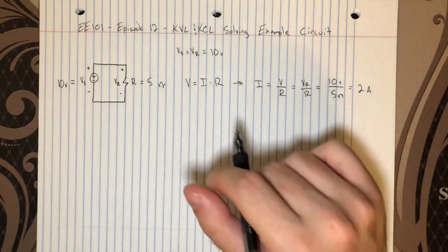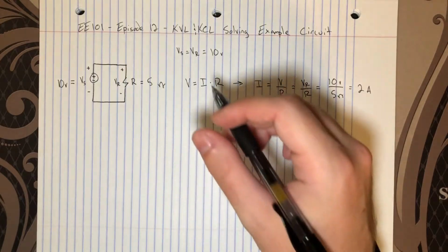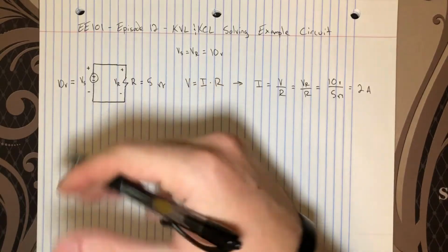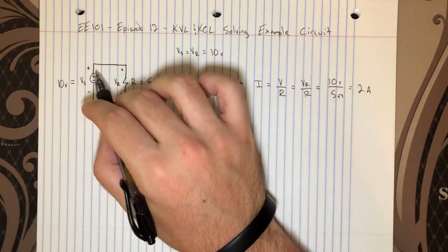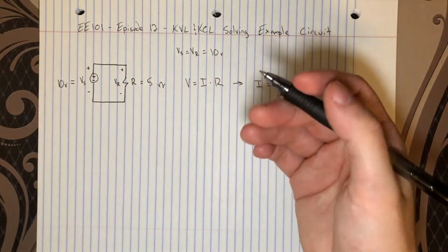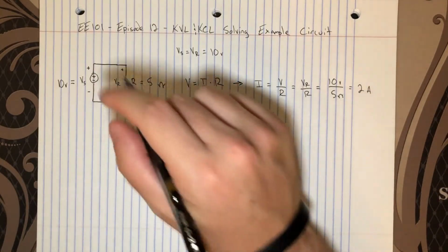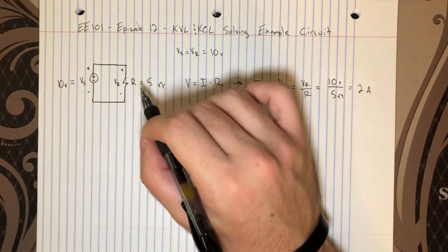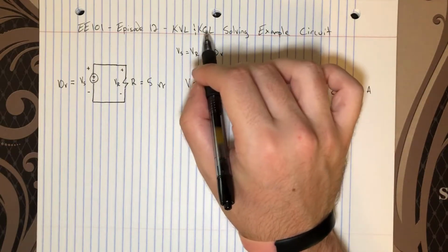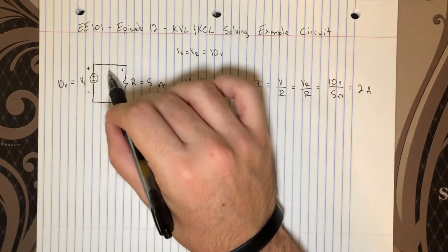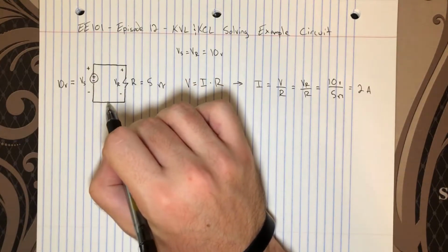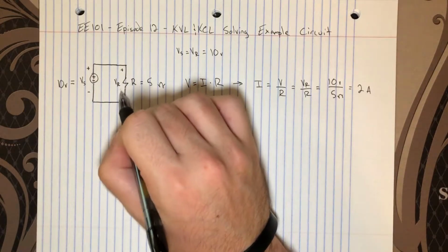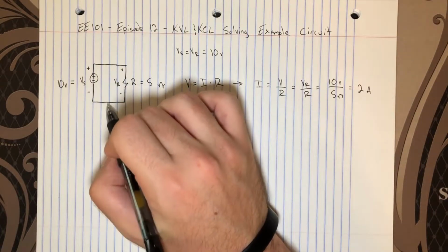And so then pause for a second and think about what I titled this set of notes. When I said that the voltage across these two elements is the same via the fact that they're in parallel, via the fact that they're connected via ideal conductors, what I was really doing there is applying KVL back of the hand, saying that the sum of the voltages across this loop must ultimately wind up in zero. And now what I'm saying is I'm actually applying KCL by saying that the current through these two elements must be the same, because if you look at either node, this side or this side, any current that flows this way from this resistance, well, it has to go through this source because there's no other path.